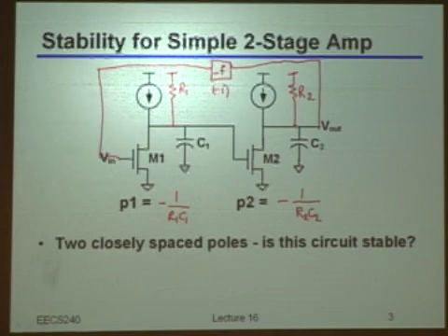So let's assume that I'm just connecting them in a unity gain configuration. Then my point is, okay, so let's even plot, right? What is the Bode plot of the loop gain? So the magnitude of T of S as a function of omega. I would have something like that. I'm assuming that the two poles are at the same spot, and I'm having minus 40 dB per decade.